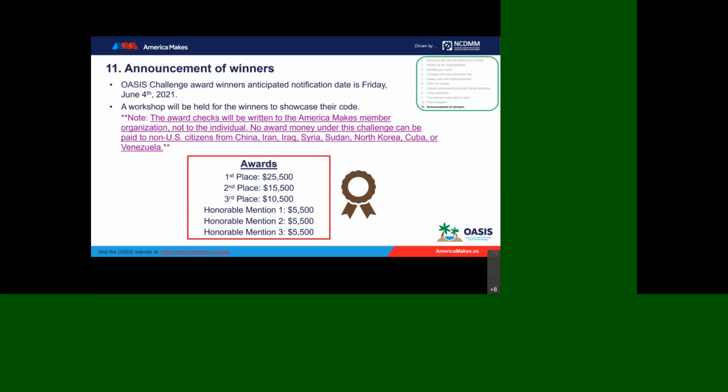So now you could imagine different ways you can cover the area across the build plate. So you could think of checkerboard patterns or space filling curves, or coming up with different ways that you can move the laser from one region of the plate or one region of the part to another region of the part, and by thus controlling the delay between one pass of the laser to the next, you can affect the part properties in the end.